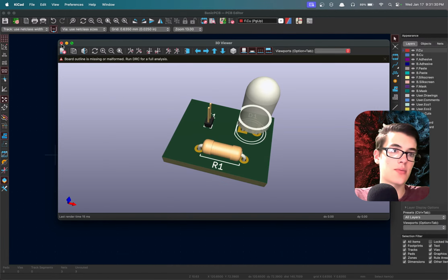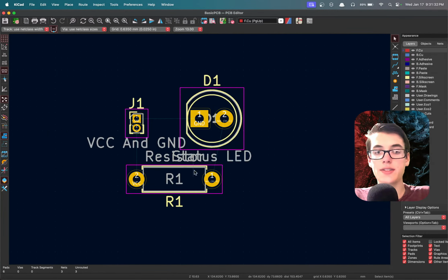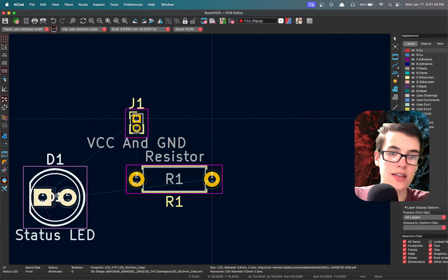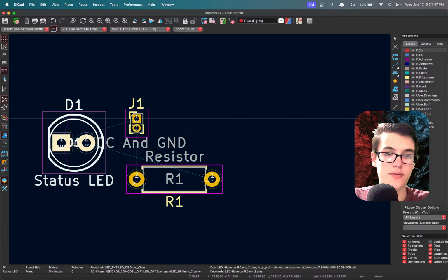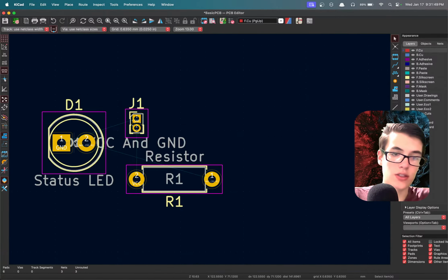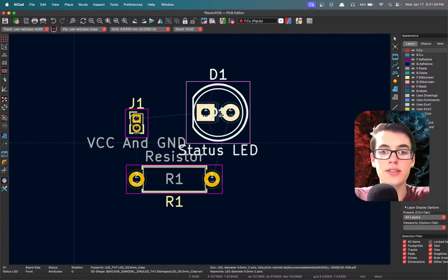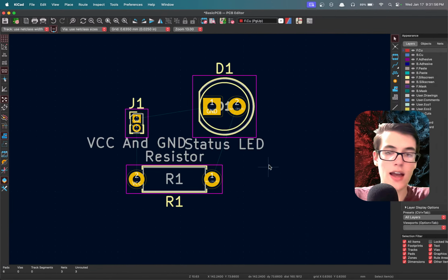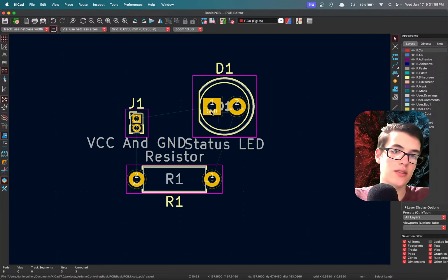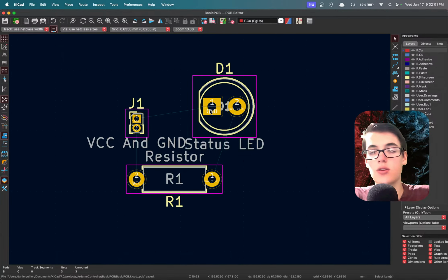So that's what I was saying about these components. Since this is such a simple design, we would like to do just a one-layer PCB, which means none of these lines can cross over each other. So if they were in that organization before, something like this, it would be really hard because these two lines cross over each other. We'd have to figure something out. Now, these lines here are obviously not optimal for how the traces are going to be routed. You can't do lines like that. Usually you have the lines going along a certain grid, so it's easier to manufacture.